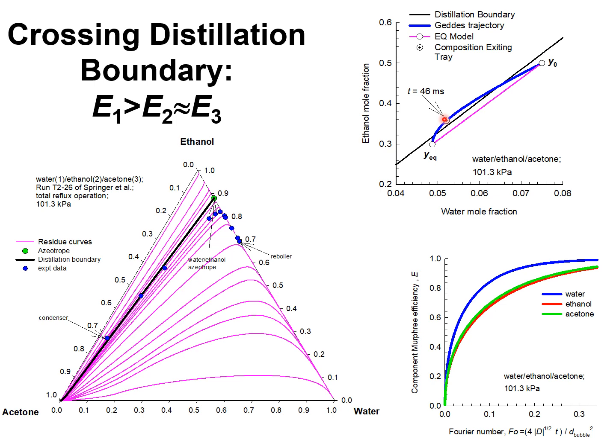If the tray dispersion height were to be tall enough such that the vapor bubbles could equilibrate, then the compositions would get back to the position shown here, and no boundary crossing would be observed.